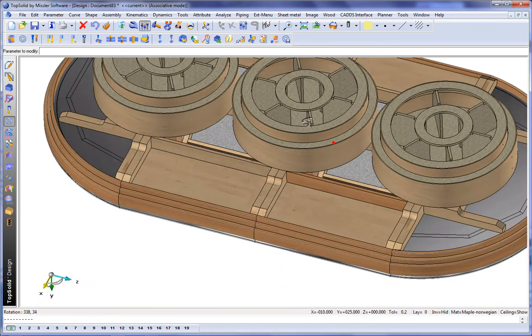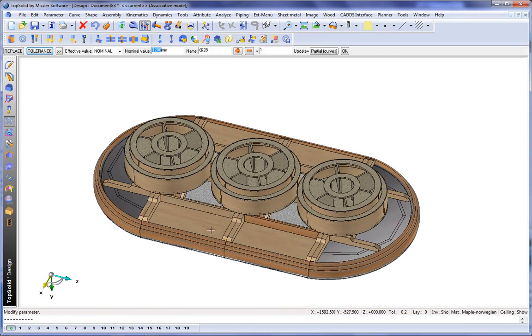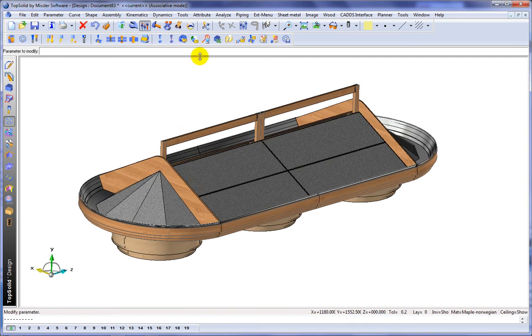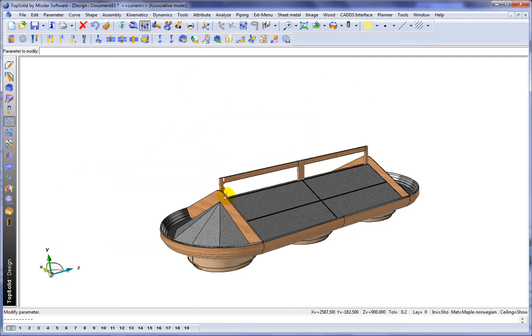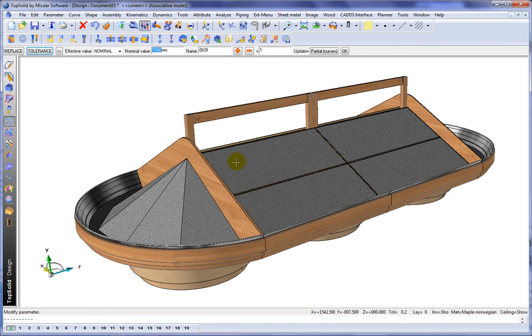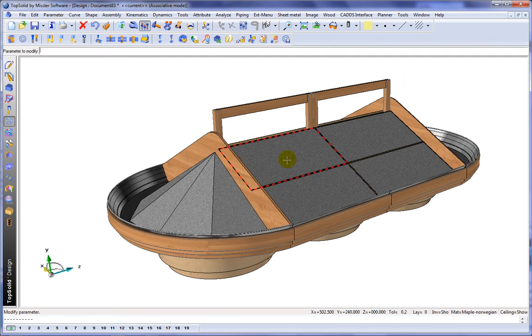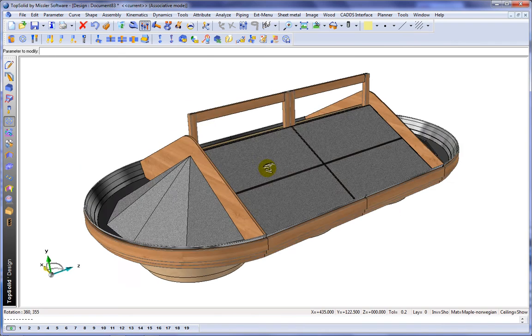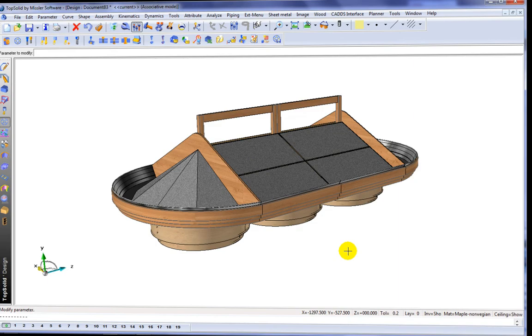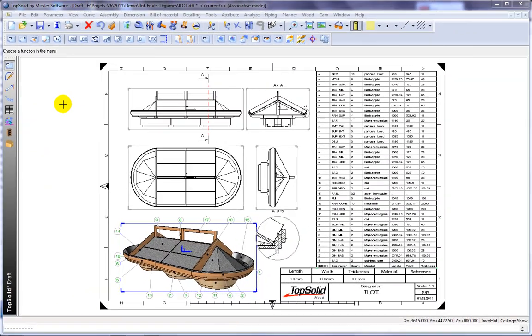Let's have a look. You should get a good feeling that by using TopSolid, you can recapture the design and make it super smart so that you can take this design and automate its manufacturing process down the road. Here we'll change it to 1500, and like that, everything updates perfectly. Cool. The last thing to talk about would be the automatic bill of material.